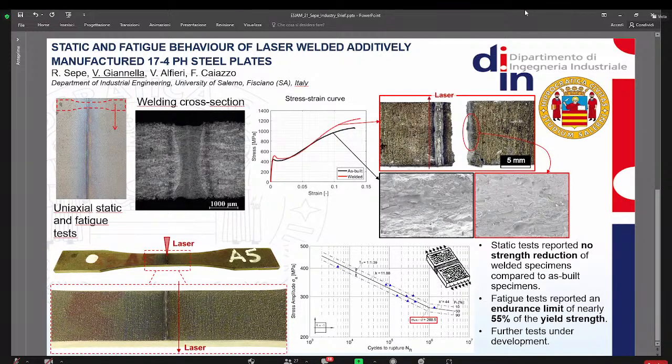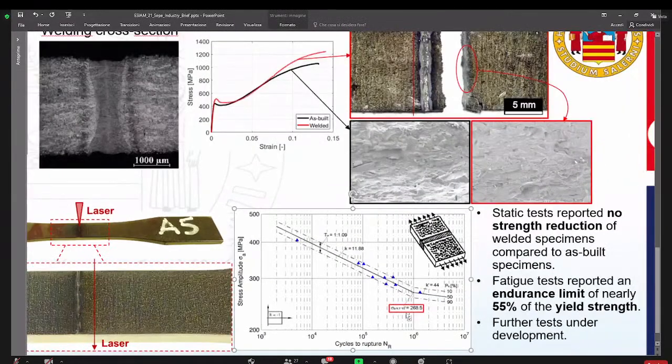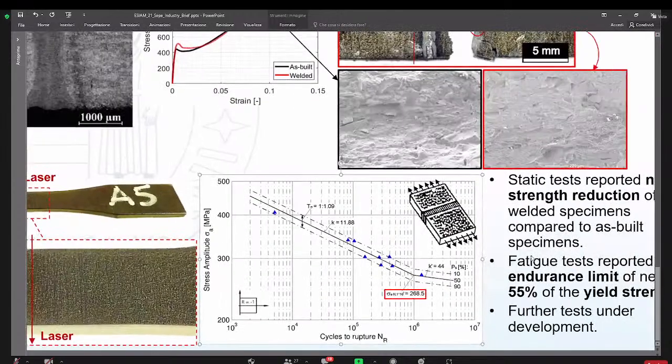Which evaluation method did you use, and how did you define the knee point and the slope after the knee point? When I take a look through the results, I could also imagine that there is no knee point, depending on how the test results might come out at lower load levels, towards the long life fatigue regime. So this would be the first one.